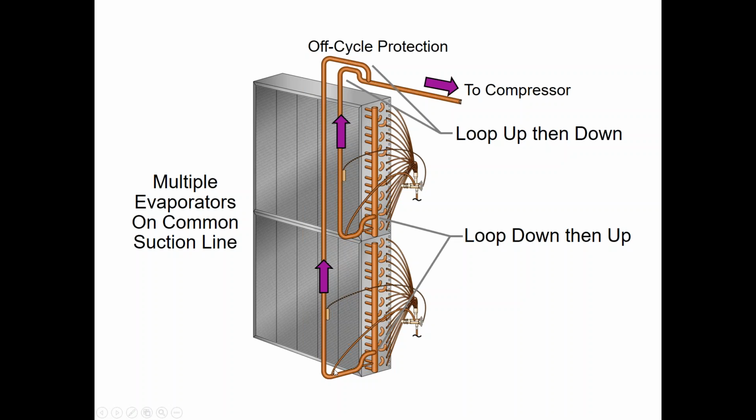So you get a mixing 90 here, you got a mixing 90 there. Hopefully by the time we get to the sensing bulb, all these different temperatures coming off of the suction header will be in one mixed common temperature state. So sensing bulb location, things to think about: don't mount it upside down, and use 2 mixing 90s. And this is when you're going in the vertical.